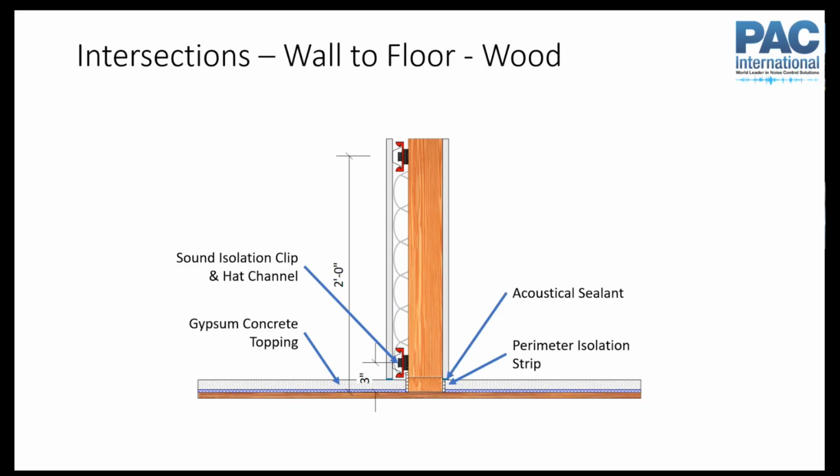The thing that's special about acoustical sealant is that, at least in theory, it is non-hardening, so it won't over time solidify and create a rigid connection, because for acoustics we're trying to keep these things structurally separate, so we don't have this rigid transmission path. So acoustical sealant will stay a little bit squishy, resilient. So you would have your drywall come down to your subfloor, probably in this case, and you'd have acoustical sealant there to seal that gap.